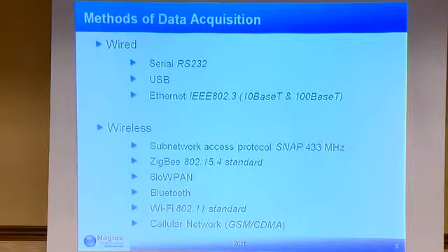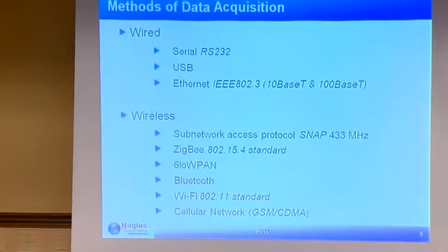Speaking of Zigbee network, Zigbee is a mesh network, that's the advantage. When I talk of a mesh network, if you want to transfer data from point A to point C, A being the sensor and C being the Nagios server, A can directly talk to C through the wireless medium, and Zigbee works at 2.4 gigahertz. Or A can talk to C through B also. A sends the data and B receives it, and B repeats it again and it goes to C. So there are many redundant paths for the data transfer. This makes the communication more reliable and reduces the error rate.